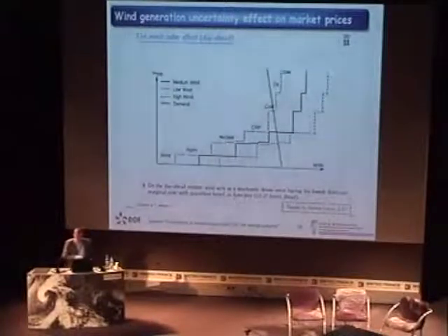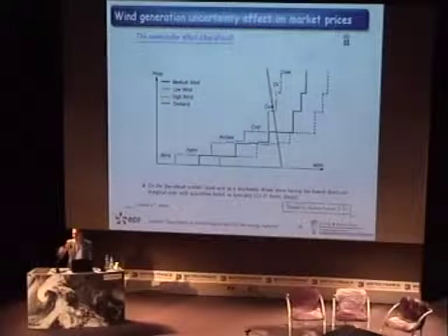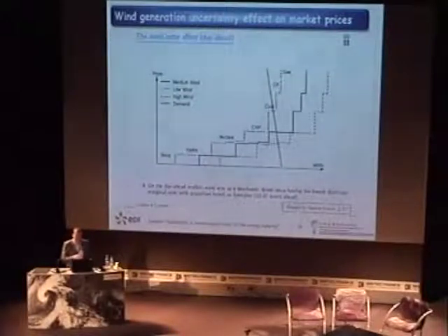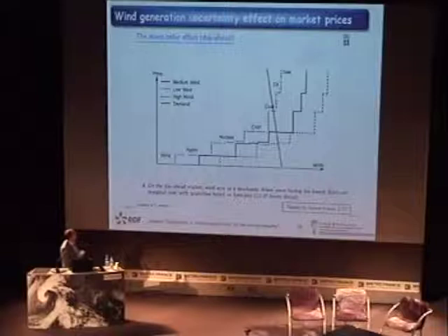And something I didn't mention before, but the general rule for planning your production means is to consider the demand you have forecasted. So you have a given demand you have anticipated for the day before, for the day after, for instance, and then the rule is to use the merit order rule, which consists simply in using your production means by increasing cost of production. So in the countries where you are obliged to use wind energy, of course it is used first. So you will have this level of wind production available for that day. And then the idea is to use other production means and to add the production of those means as long as you don't cross the curve for the demand.